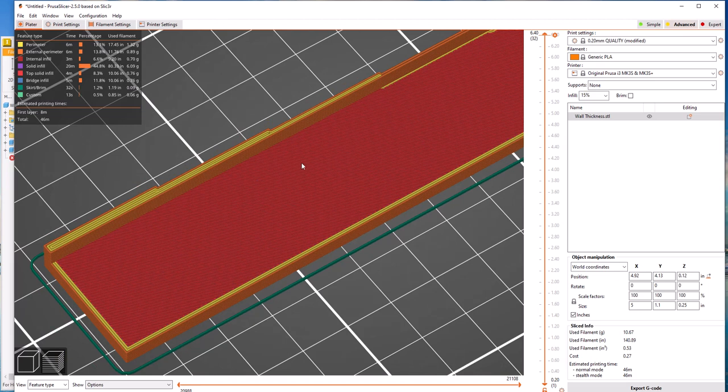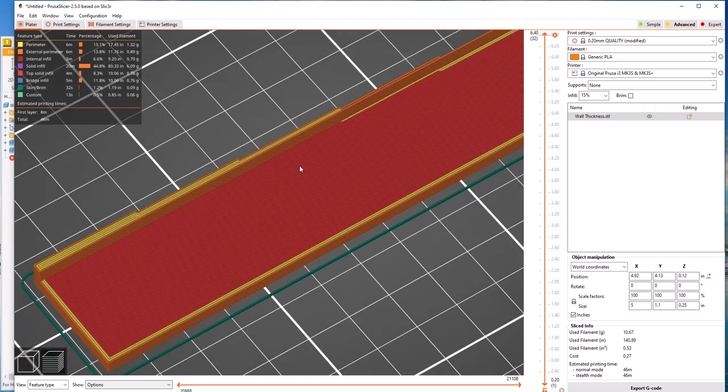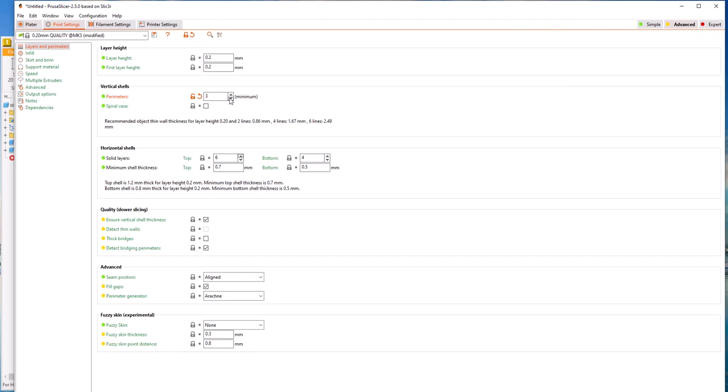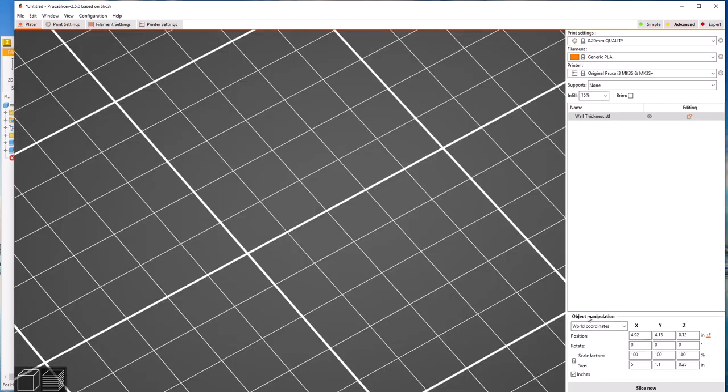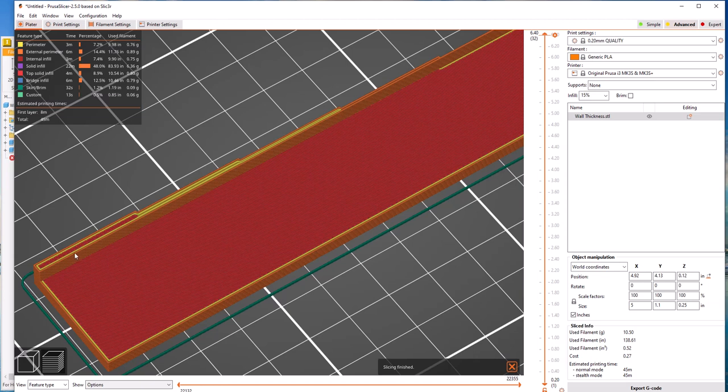Why are we looking at this wall thickness concept? Because a lot of times people will design a box, a cabinet, a shelf, a bracket, and they just choose a standard wall thickness, 1/4 inch thick. I don't know, maybe that's what the material is going to be, so you need 1/4 inch. Maybe you're just picking a number because you're not sure. And what can happen is you can have extra material that you don't necessarily need. This 2-wall perimeter has infill going into this dead space in here.